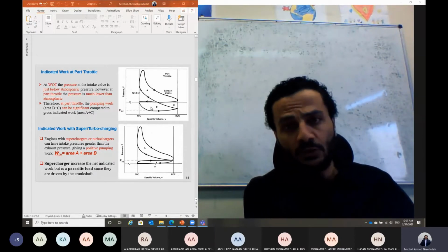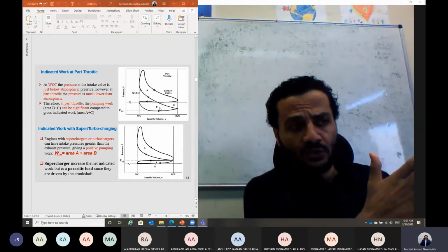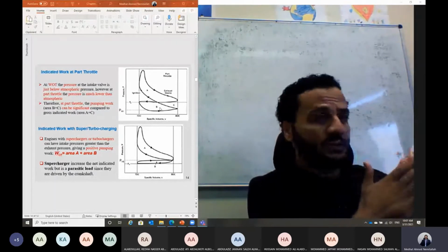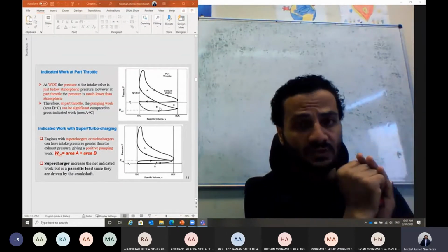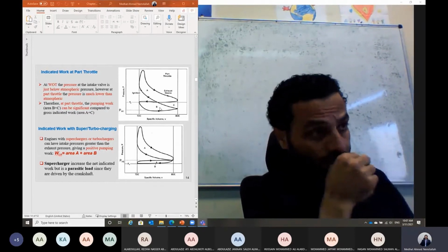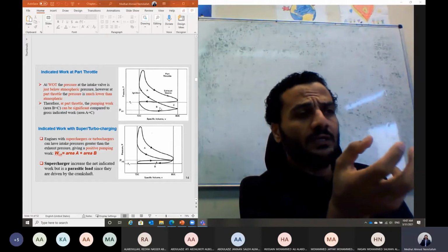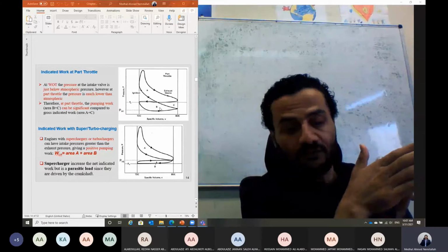The friction loss power also includes the rubbing friction losses, the friction losses between the piston as it is moving inside the cylinder. So we have friction between the piston and the cylinder wall. Also, Shabab, we have mixing between gases, and this is actually a totally irreversible process. So we have friction losses in the gas phase itself, between the molecules.